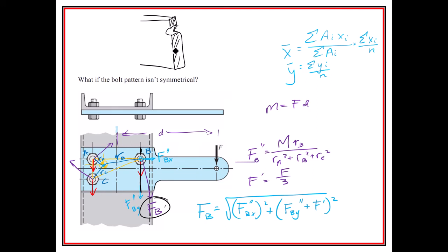For one thing, the neutral axis will be shifted down. It isn't going to be the geometric center of the width, so we need to take the neutral axis about that. We also need to take the I about that. And so when we go to make the C, there's going to be two different C's in the MC over I, right? So sigma equals MC over I.